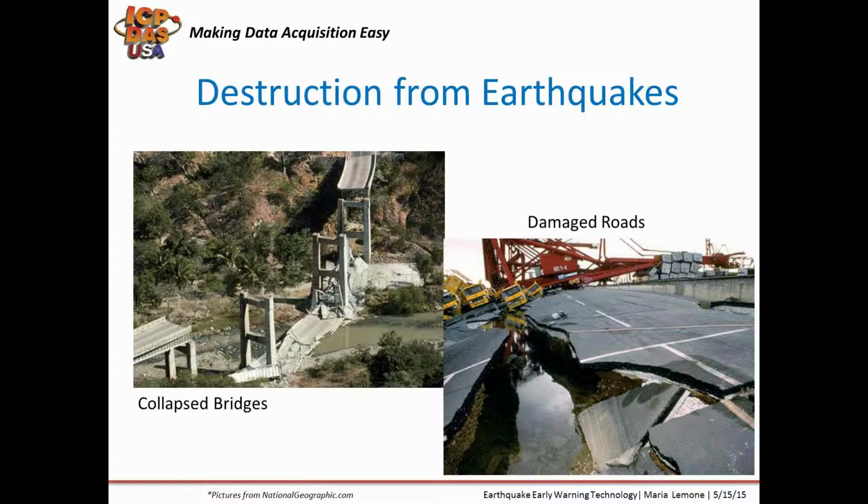Seismic switches are used to acquire seismic activity through MEMS accelerometers, which measure the force of acceleration. Seismic switches can be used to alert drivers on a bridge about bridge destruction so people will know a bridge is unsafe to cross, through programmable controllers and web-based LED displays. They can also help train operators to stop a train in case of seismic danger. They can also be used to stop elevators, shut off gas valves, start generators, stop plane landings and takeoffs at airports, and to notify fire stations about earthquake activity.